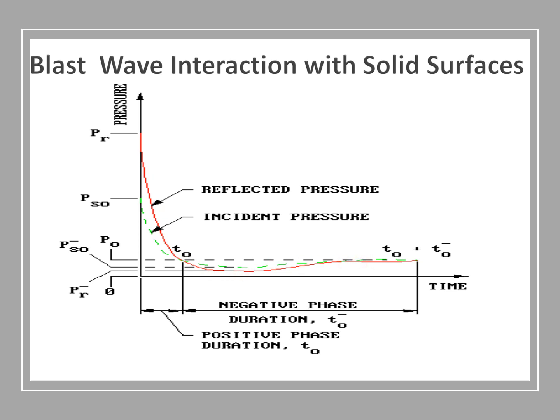The difference between the incident and reflected pressure in an infinite surface is shown in this illustration. The pressure that is reflected can differ significantly from the pressure that is incident, as demonstrated. This magnification may result from a number of reasons, including the structure's shape and the kind, size, weight, and distance of the explosive. The reflected pressure pulse shown in the figure is typical for infinite plane reflectors. To apply for design, there will be slight modification as will be shown later in the upcoming videos.